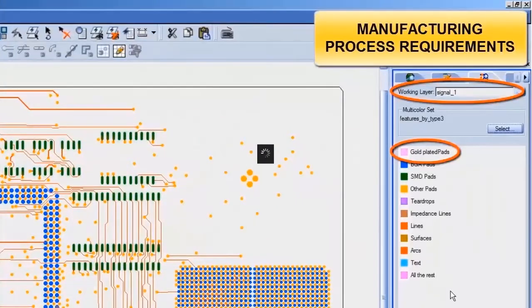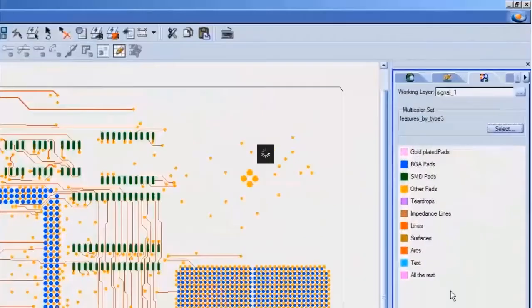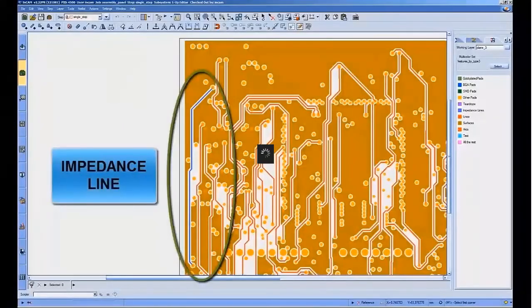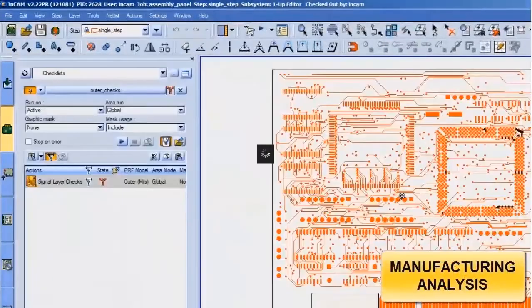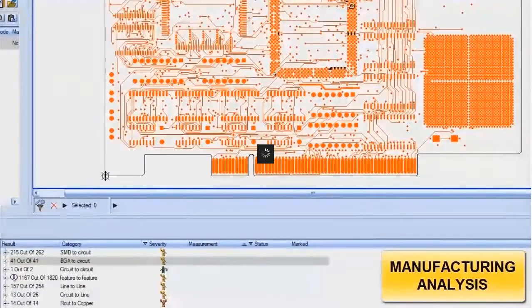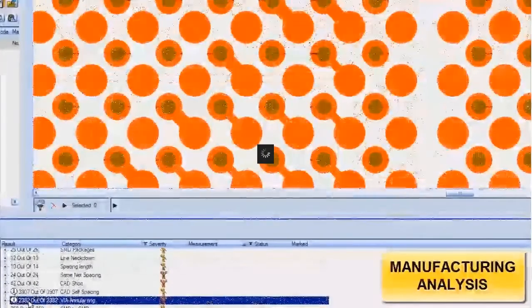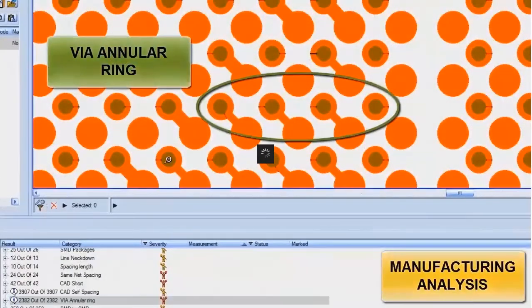Surface finish definitions are defined and can be highlighted immediately for use in the tooling generation process, as can controlled impedance features. The process engineering specialist will always want to run his own DFM analysis, taking advantage of the intelligence in the ODB++ data, so as to validate manufacturability, but also to maintain the rules according to the actual manufacturing processes running in the factory.